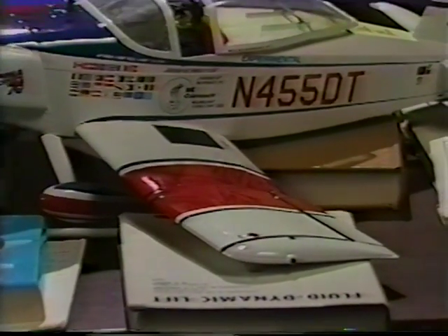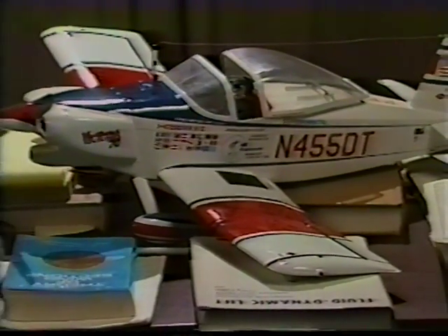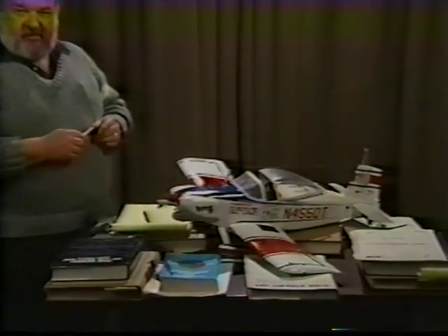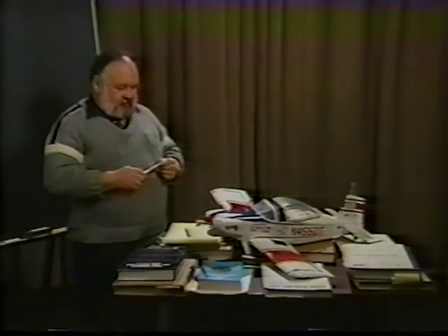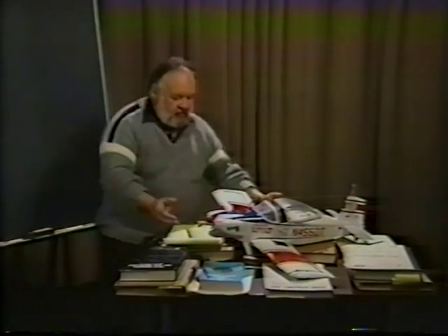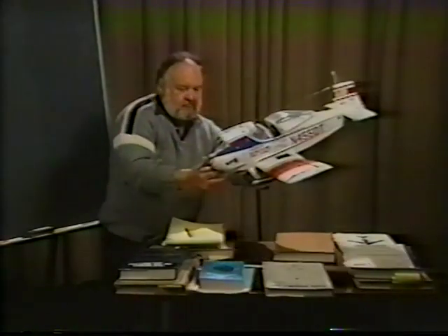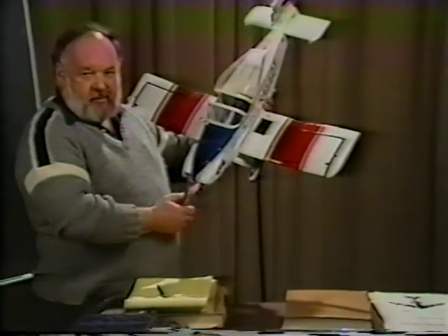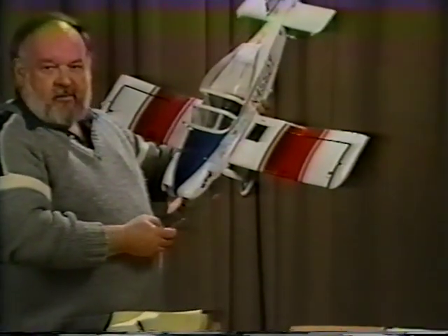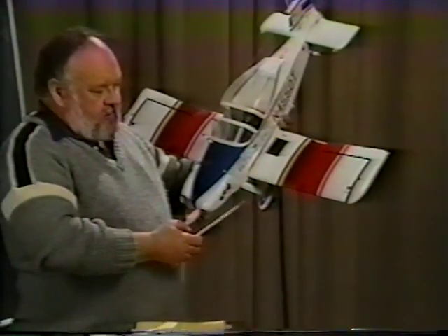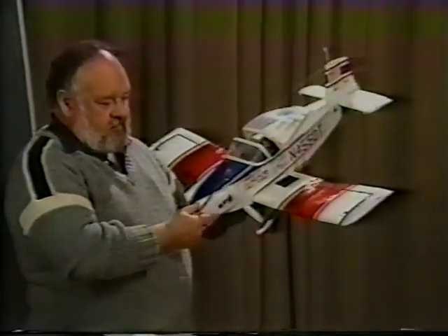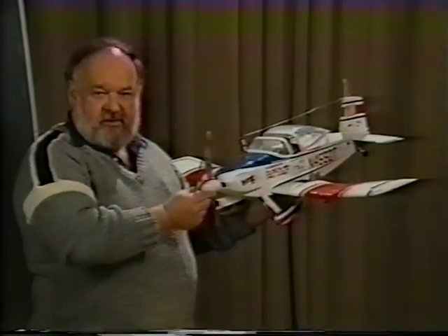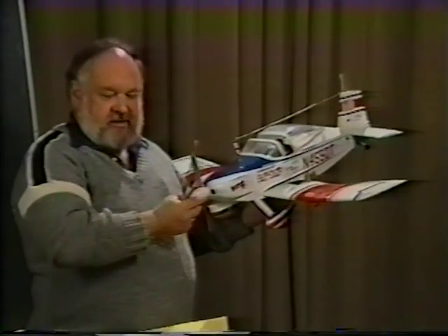Here's a model of a T-18 homebuilt. It's a very well designed aircraft by John Thorpe, quite popular, but it has a number of features on it that might demonstrate a little of what we've been talking about. For example, it has a straight chord wing, essentially a rectangular wing planform, straight leading edge. It does have polyhedral to the extent that the inboard section has no dihedral and the outboard section does.